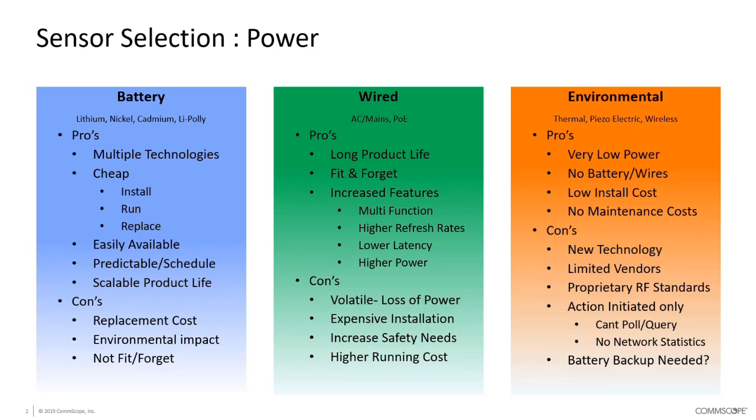So what you're seeing is a hybrid approach where maybe they're generally running on piezoelectric, but they maybe have a battery backup so that you extend the battery life, but you still have a lot of the capabilities. They also tend not to be using any of the more standard protocols, obviously because they are using very low power, and some of the radio technologies out there today that we've talked about tend to be designed to run off a battery. They tend to have slightly higher power. So what you'll see is that the RF standards maybe are more proprietary or are using a lower frequency so that they don't have to use some of the more complex modulations.